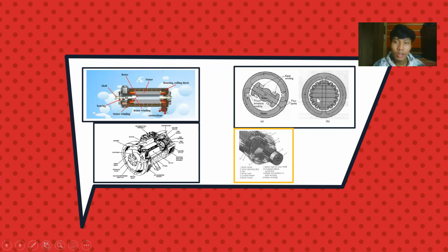And the rotor construction: the cylindrical pole type for high-speed generators consists of grooves for the field coils. The grooves are divided into polar pairs. The salient pole type is for low and medium speed generators. The protruding pole consists of a polar core and polar shoe.